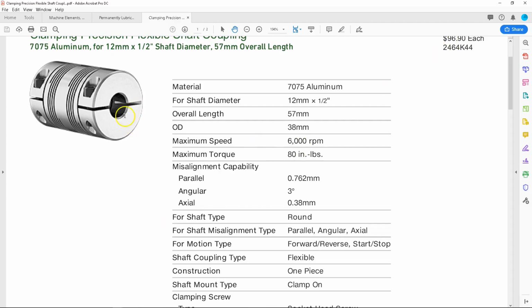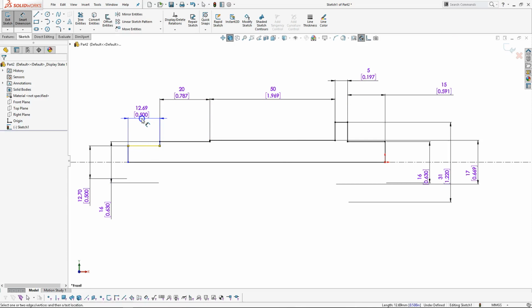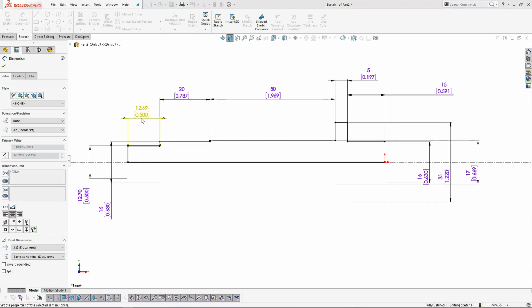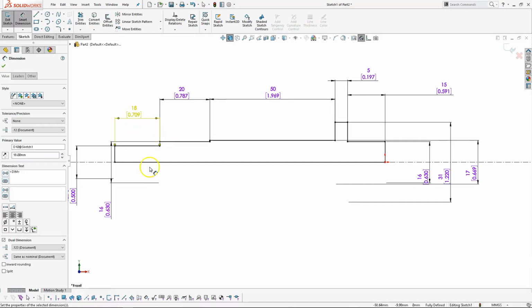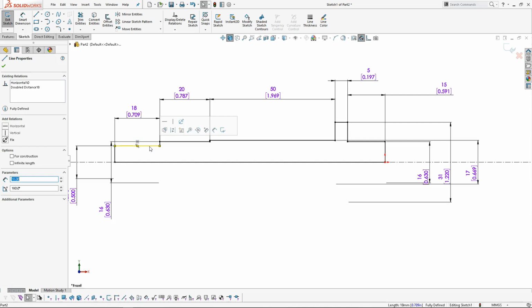I was looking for then kind of the depth that the shaft could go, but we'd go at least 1 times the diameter. So 1.5 would be 18 millimeters. So that would be a good starting point. Then we could see what we can do. So for our critical faces, then we would need the alignment to the shaft through the bearings, but the bearings really front and back.